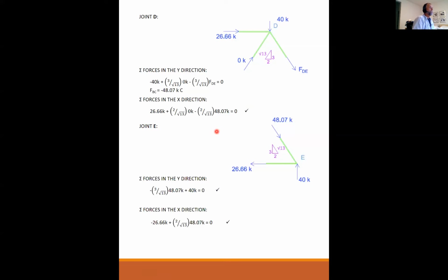You have 3 degrees of freedom. Sometimes the way you find the answer is you sum the moments about, say, A, and you can sum the moments about, say, D, and then sum the forces in one direction. It's not always moments, X and Y. It's just 3 independent methods to get to all of your unknowns.